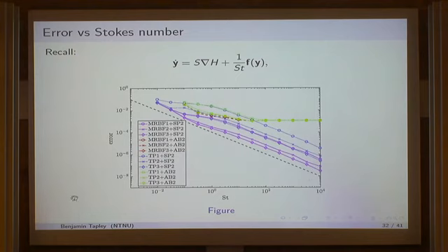So this is really the magnitude of the fluid forces along the x-axis. Because we're using a splitting method, we actually pick up this order epsilon accuracy as we increase the Stokes number in our splitting method solutions. So the pink and blue are the splitting methods, and the Adams-Bashforth is independent of the Stokes number. So we gain accuracy as the Stokes number increases.